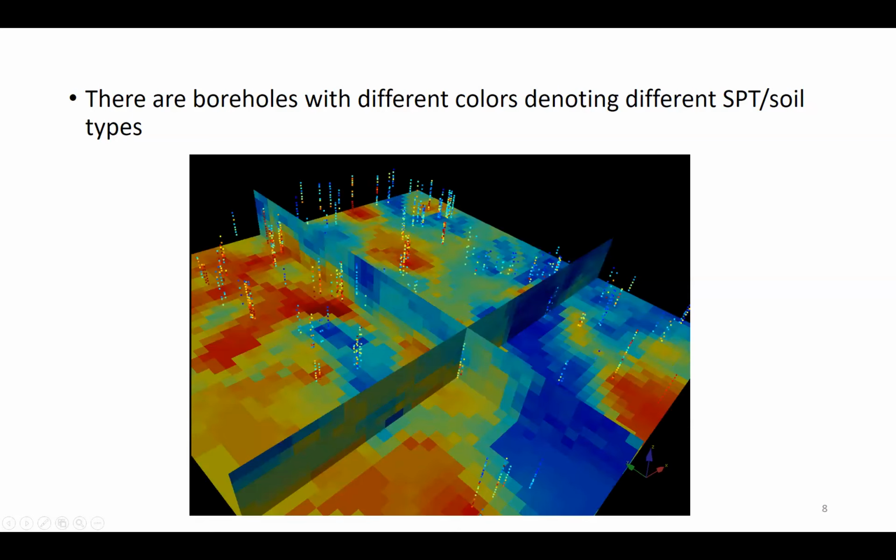So we think that geostatistics provides a more realistic visualization of the subsurface profile. And you see the validation between the boreholes and the sections provided in simplified linear models. And geological engineers or geotechnical engineers can detect problematic soil variation, which would otherwise not be identified by linear interpolation.